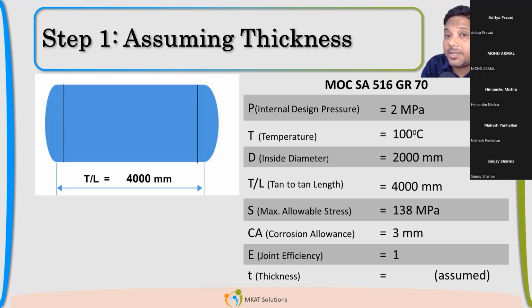So your design temperature for both of these cases will be different. If you are not given separate design temperatures, please always clarify with your client, designated agent, or process department what your design temperature for external will be. To be on the safe side, you can take the same as the design temperature, but always clarify. Always get clarification from the client.